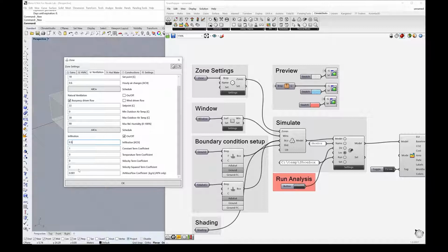If you want to know more about this and what parameters you should set, you can always look it up in the EnergyPlus Input Output Reference, where there are good default values specified. The EnergyPlus default is always using this constant term, so this is what we also recommend moving forward.